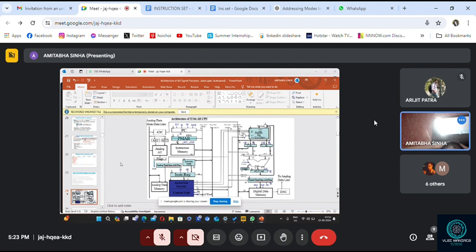Another thing is very important. When you do integration and differentiation, integration is very easily done by capacitor circuits, and differentiation can also be done by a capacitor in a different way altogether. Now, integration and differentiation are done using the physical properties of the devices. What is the physical property of the capacitor? It stores the charge. That means it accumulates the charge.